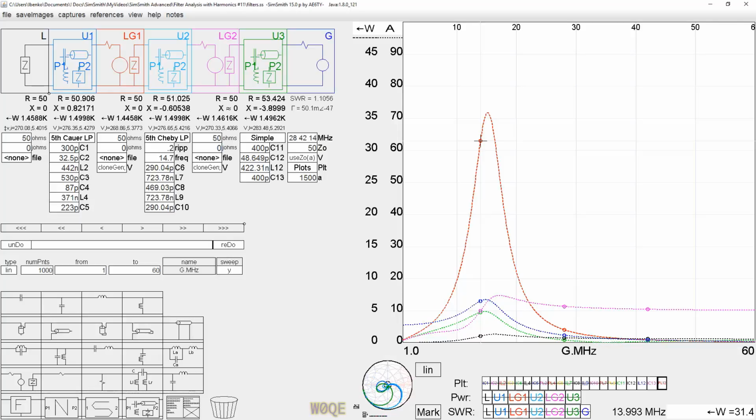And this could be somewhat problematic in a ferrite core. In an air core inductor, it's no problem at all. But if this current, which was like 13 amps, rose to be like 20 amps, we'd have to start thinking about winding it with something better than 12 or 10 gauge wire if we don't want the inductor to get too hot. So, anyways, this was a little lead-in to the next section, and in the next section we'll put the actual filter in there. We'll put the variable loads in there, the harmonic generator, and see what surprises await us.